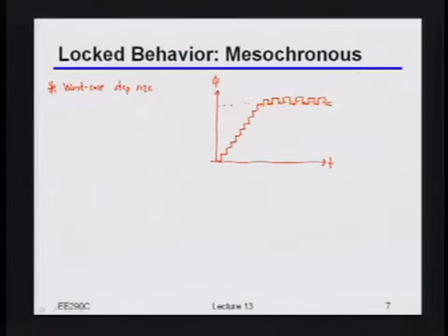You don't necessarily have a ton of control over that. I guess you could change the rate at which you're running the loop and things like that. But basically that dither has to be there, and I think in this particular context, it probably doesn't change the overall performance all that much. Maybe there are some second order effects in terms of the jitter filtering, but largely speaking, I pretty much have to be jumping up and down every cycle, because if I'm not, then things are even worse. I'll maybe show that in more detail in a second, but you can imagine if I'm not going up and down every single cycle, that means I'm taking multiple steps up and multiple steps down, which means the dither is even bigger.